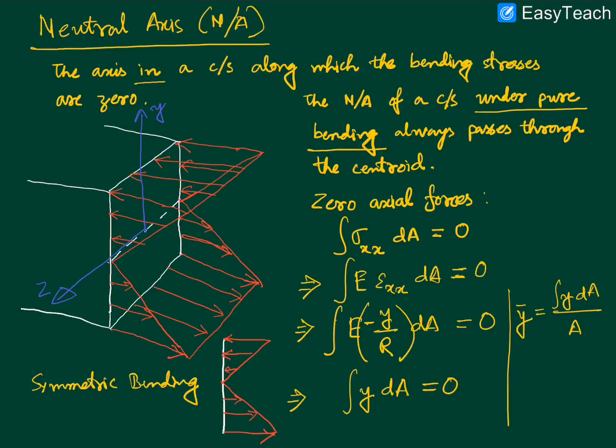So you note that whatever I have drawn just here is nothing but the front side projection of this three-dimensional picture. I repeat, whatever I have drawn here is just the front side projection of this more complicated picture in 3D. And you note that this particular point is just the front end view of the point which denotes the neutral axis. Now I want to import this idea directly to the case of unsymmetric bending.